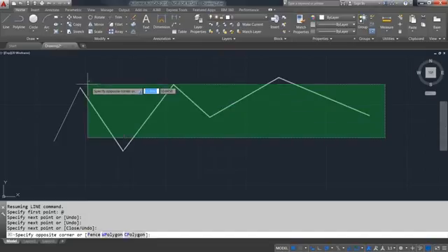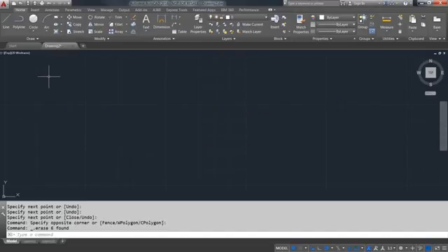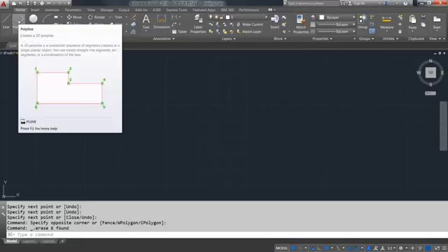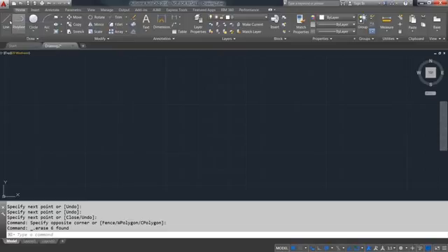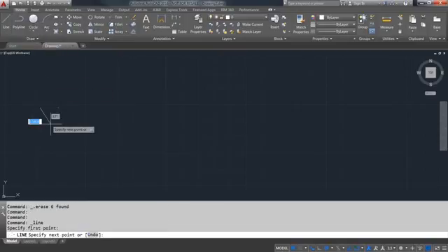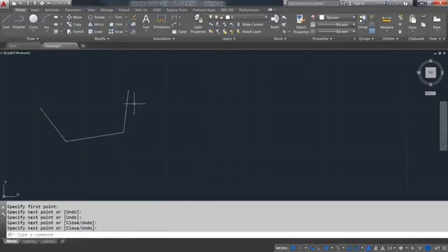So let's just get rid of all these lines and move along. So the next thing we come to is the polyline. Now, in a lot of respects, the polyline is like the line command in that you can draw a bunch of segments with it. However, with line, each individual segment of your continuous line path are separate objects. There's a line, and I can pick just one individual line from that and get rid of just those.